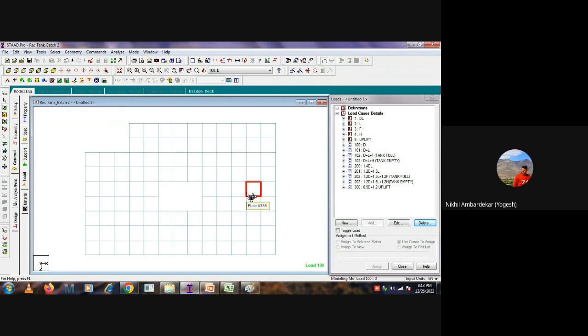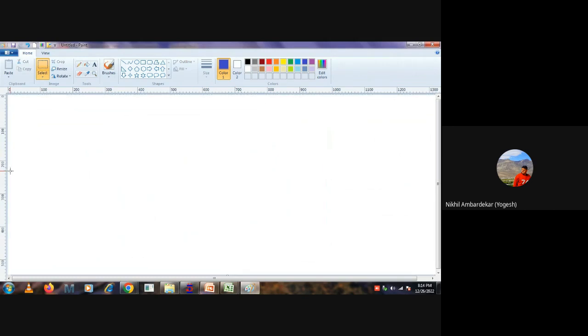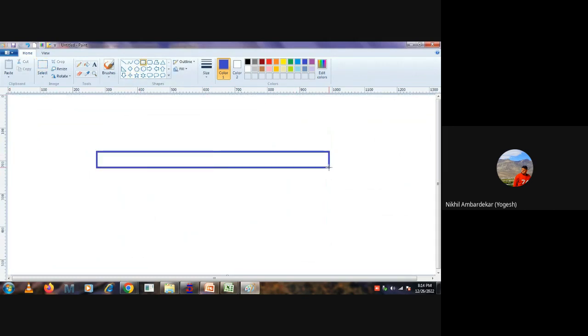And sir, on the top slab we have considered the live loads. Likewise, if there is a vehicular load, how do we add it in our loading conditions? In that case, first you need to find what is the load coming from that vehicle. Suppose I draw a section of the roof slab. This is support, this is support. So this will be one tire, another tire, load, load. You should know what load is coming at a time, and whether it is possible that two tires come at the same time or only one at a time.